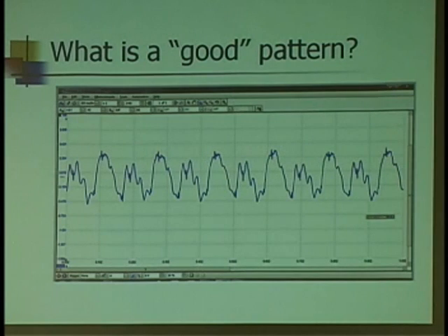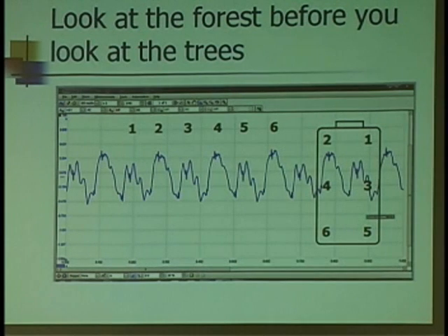So now I want to take a look at what I'm testing. What about the engine and the system that I'm testing? Well, let's take a look at the firing order. Anybody see anything now? One bank is low. One bank looks one way, the other bank looks the other way. So however the tailpipes, the plumbing might be run, or the exhaust manifold might be designed, can affect the way this pattern looks. Now if I saw one of these, of the three, chopped in half, that might throw a flag up that needs investigation.